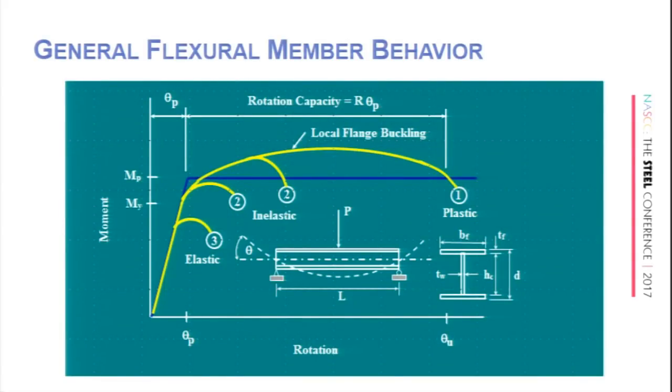So back a couple years ago when I was getting my PhD, I was asked to look at a new material that was being developed for the Navy, called HSLA 80, high strength low alloy steel, 80 KSI yield, and about 100 KSI ultimate, because they were looking at building their structures, mostly all floating in water, out of this material. So we wanted to understand what changes we would see if we went to an 80 KSI steel. That was a nice project, but what it really led into not that many years later is your HPS 70W for bridges. Then they developed 100W, and then I think they finally rolled back down and developed the 50W. And the W stands for weldable.